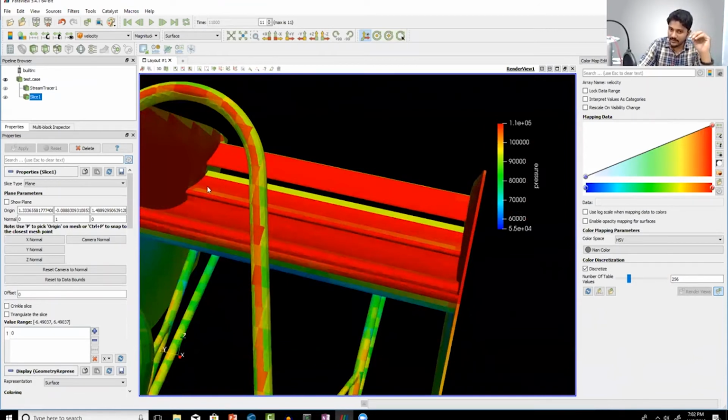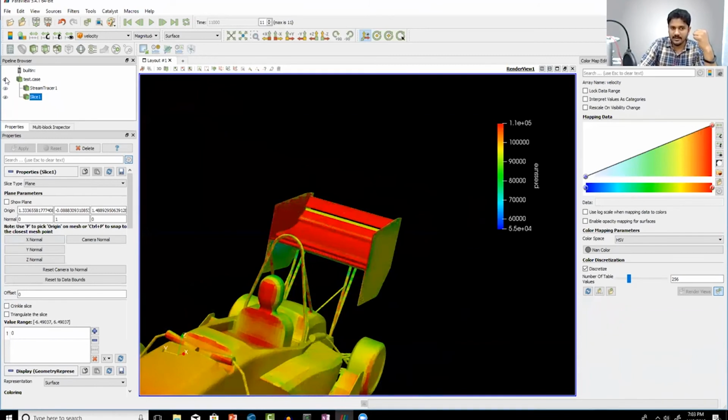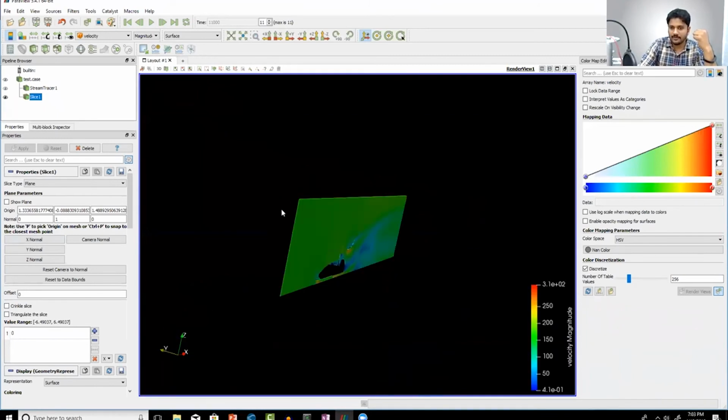So in this case, there is supposed to be a flow passage which has been blocked. Why has it been blocked? Well, during the process of surface cleanup, I think the student accidentally just closed this part. Because of that, there's no flow path there, which is bad, which means the solver thinks that this is an entire wing and there's just only 2 layers. In fact, there are actually 3 wings here. And you can understand that just by looking at the cut plane.